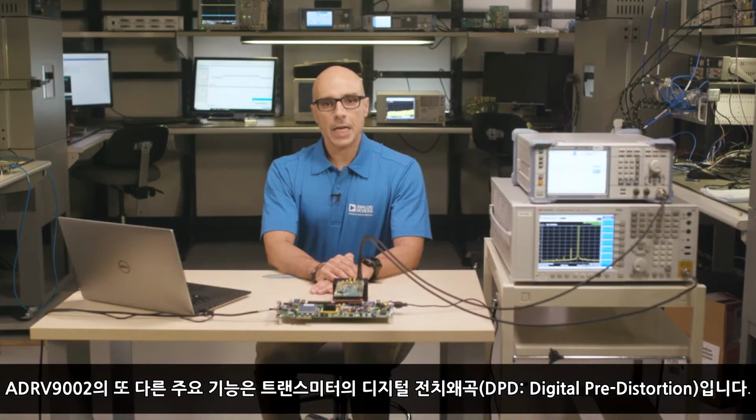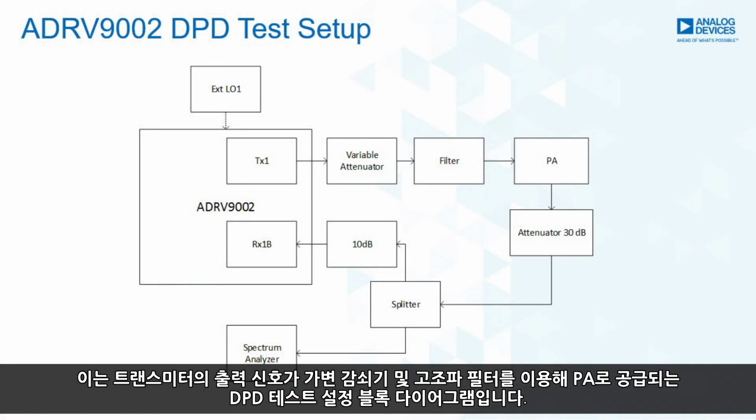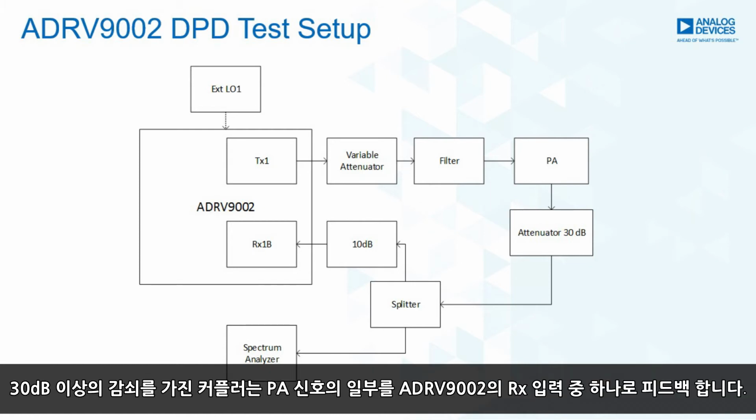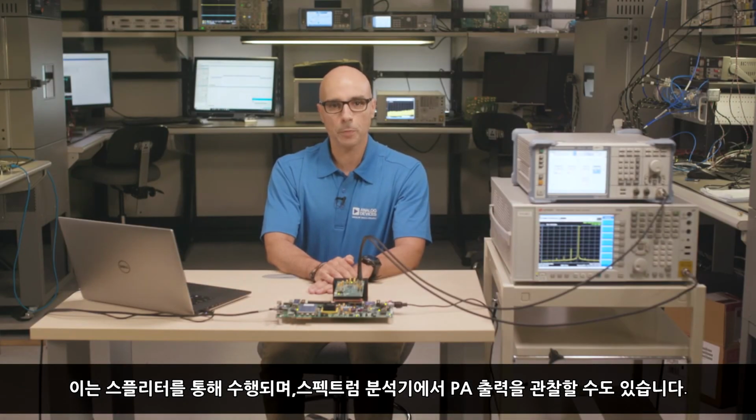Another key feature on the ADRV9002 is the transmitter digital pre-distortion, or DPD. This is a block diagram of a DPD test setup where the transmitter output signal is fed to a PA using a variable attenuator and a harmonic filter. A coupler with 30 dB attenuation feeds back a portion of the PA signal to one of the RX inputs on the ADRV9002. This is done through a splitter, where we can also observe the PA output on a spectrum analyzer.